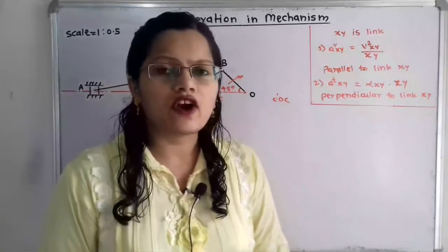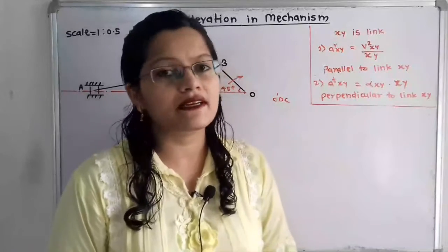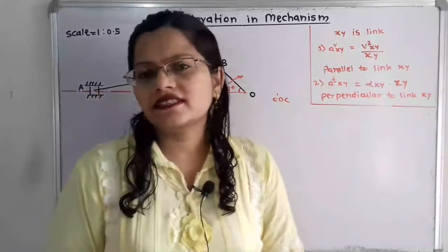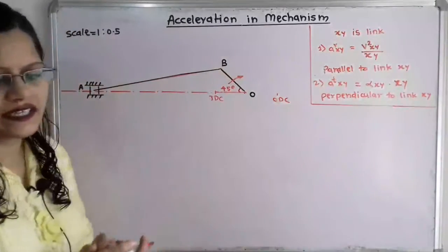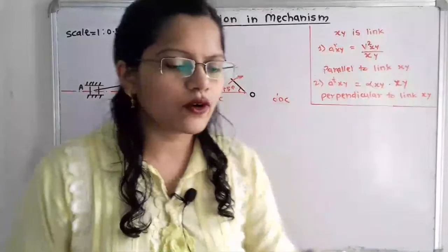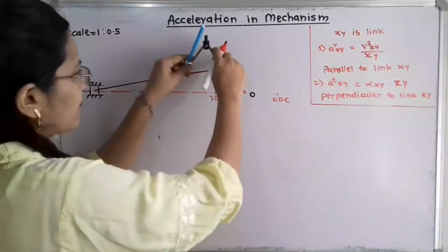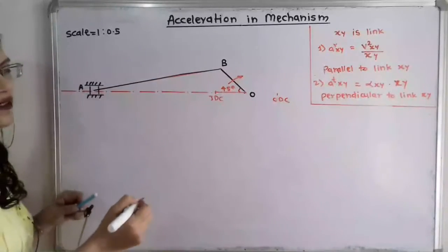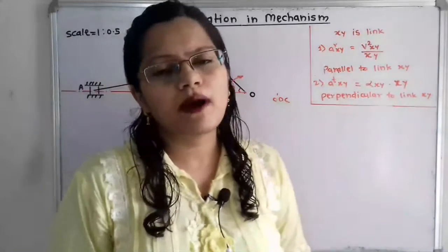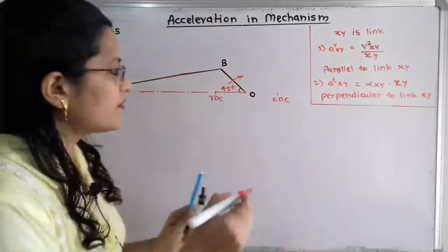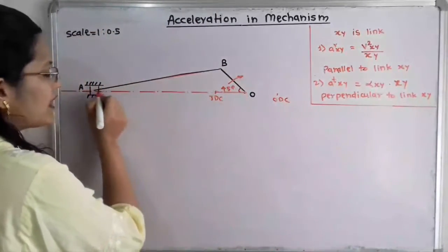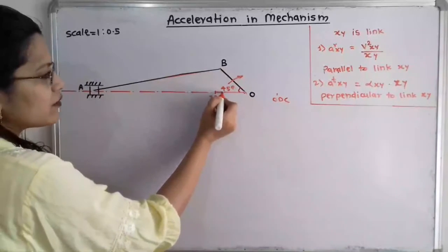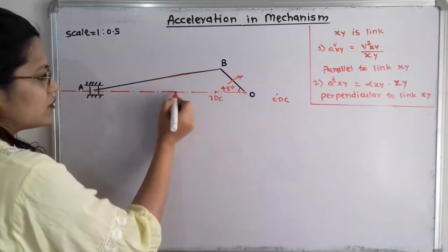Now for the connecting rod, distance is given 600 mm and which is equal to 60 cm. But here as per the scale 1:half we have to take 30 cm. So in the compass we are going to take here B as a center and we will mark here one R at a distance of 30 cm. Now here we have to mark here the point. So from the fixed point O we have to draw one line. And this is the line passing through the center O. That's why we are going to draw this line in the form of dash and dot.